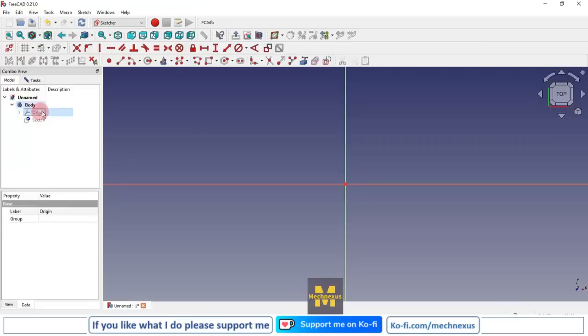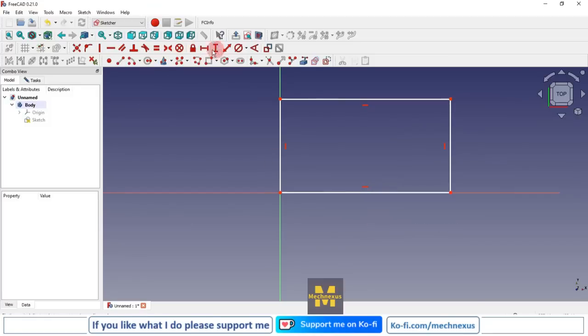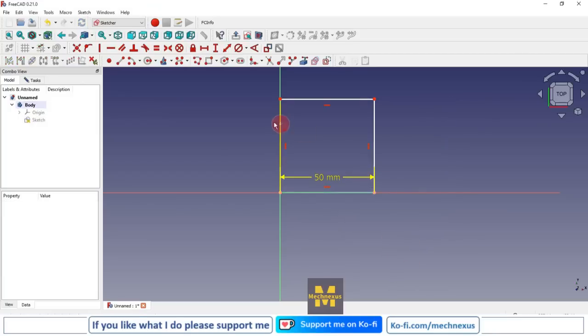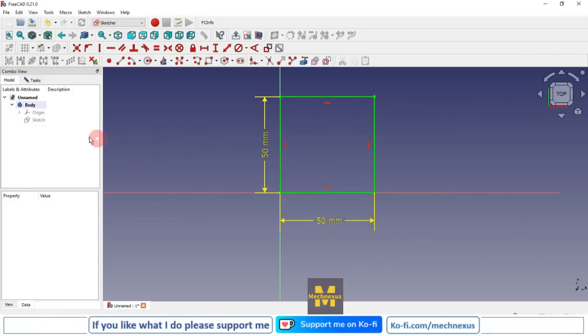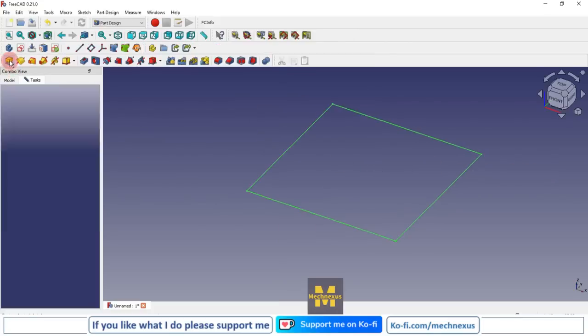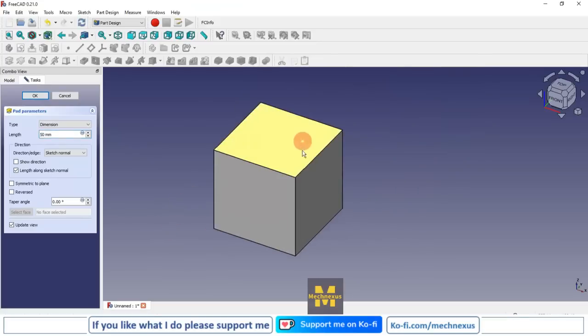Now I will simply create a rectangle and give the dimension of 50 mm horizontal and 50 mm vertical. And now I close the sketch and select my sketch and click on the pad, and I give the thickness of 50 mm.